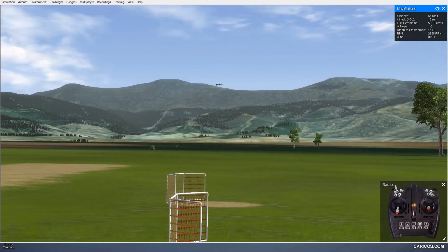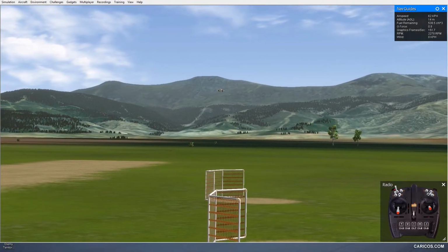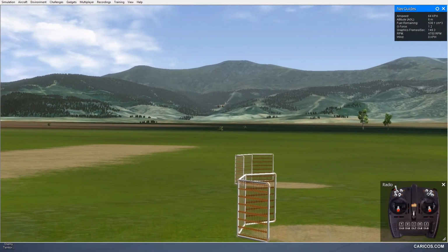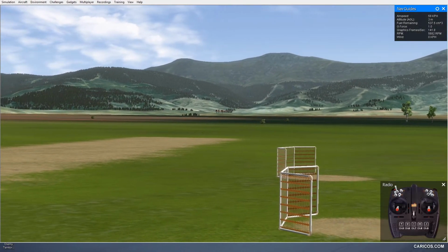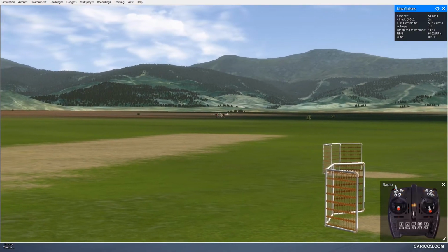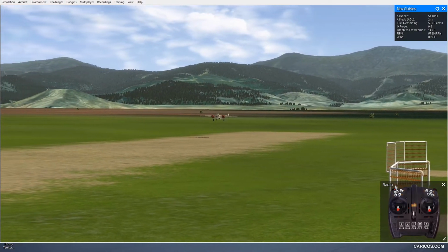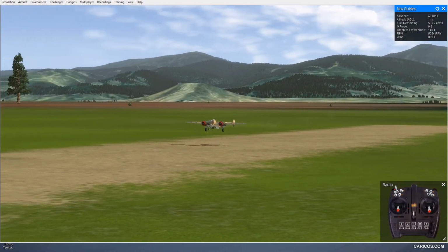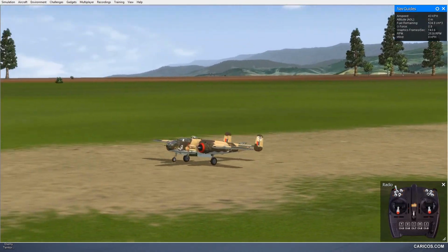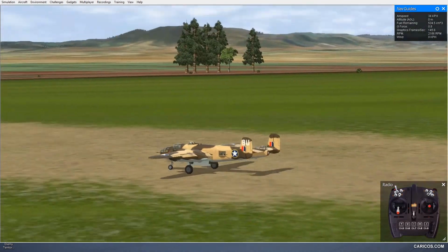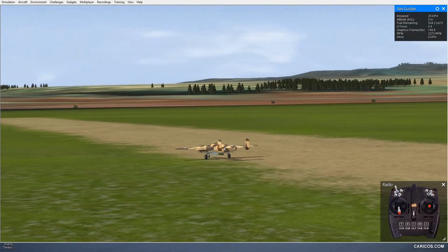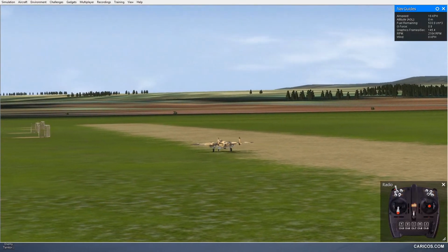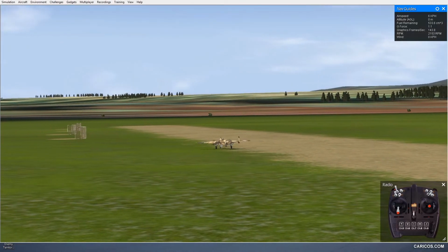You don't want to go too far out and you want to maintain, let the plane sink, and then as soon as it gets down to a certain height, start to apply power back in so that you can get the plane slowing its rate of descent. And then just when it touches down, we're applying less and less power and more flare to get that descent rate and ground speed as slow as possible. And that's how you do it.